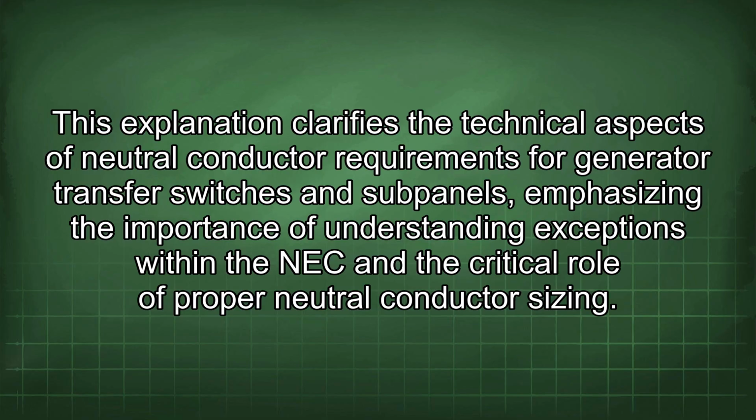This explanation clarifies the technical aspects of neutral conductor requirements for generator transfer switches and subpanels, emphasizing the importance of understanding exceptions within the NEC and the critical role of proper neutral conductor sizing.